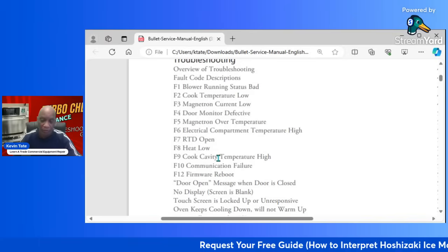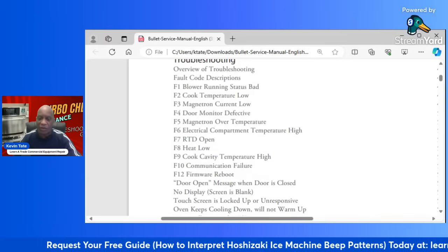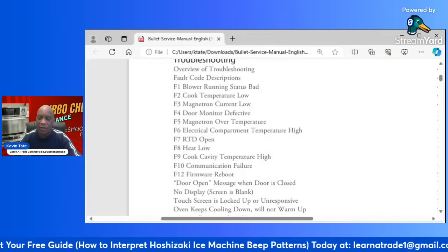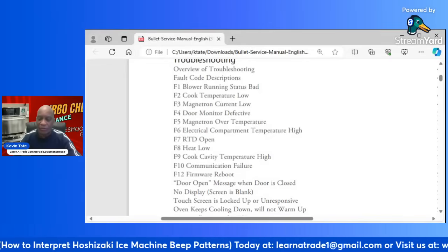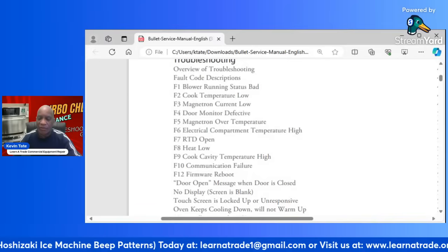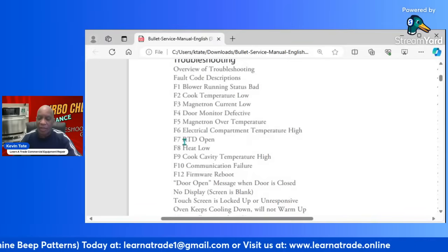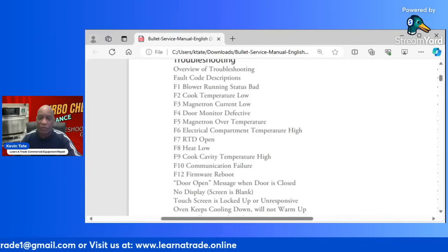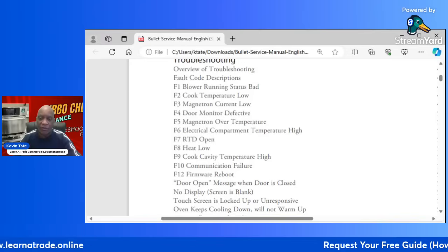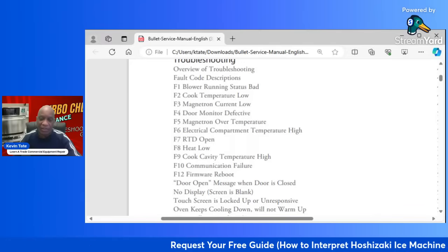And those are something that usually can be taken care of on site, because of the heat that these put out all of the time. That side RTD is usually very hard to unscrew and get out, but it depends on letting it cool down, and then getting it out of there.